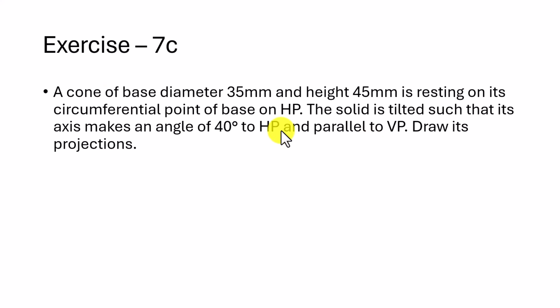So to create the cone for the given condition, first create a circle and then create a new plane at a height of 45 mm and create the axis point. Then use the loft command between the circle and the axis point so that you can create a cone. Then rotate it based on the axis of rotation created on the first sketch. Let's do it in Autodesk Fusion 360.